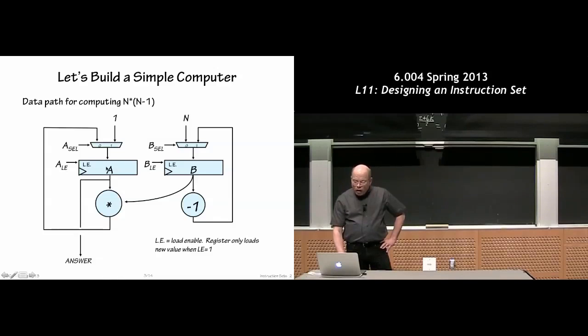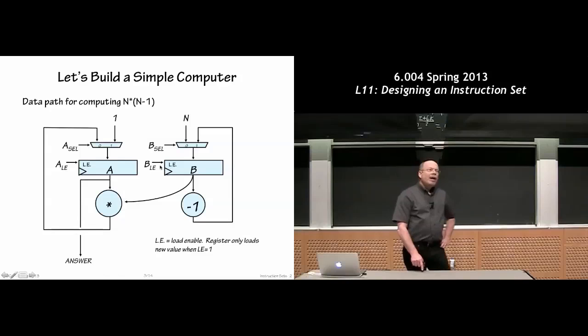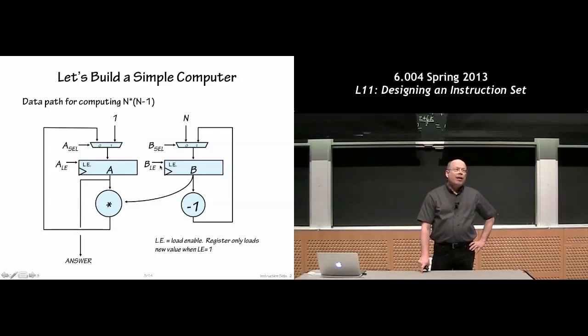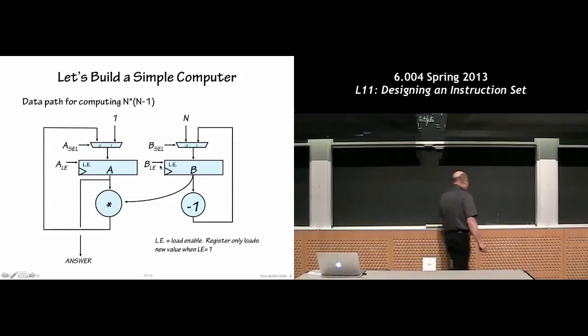These are two what we call load-enabled registers. You can see that in addition to a data input and a Q output and a clock input, they have a separate input called LE, which stands for load-enable. And when that signal is high, we actually load a new value into the register. And when the signal is low, we load an old value. The register value doesn't change. We actually are ending up loading the register all the time.